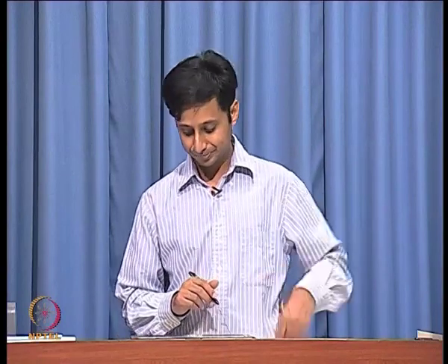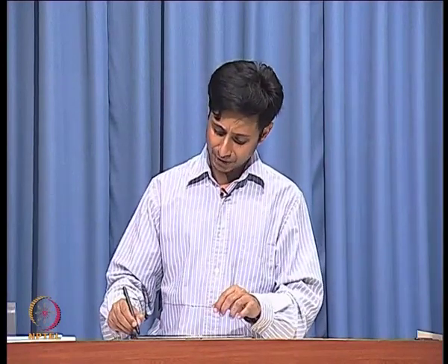So, what is your guess? How do you create a low impedance? If you look into the drain of a MOSFET, you see high impedance. If you look into the source of a MOSFET, you should see low impedance, right. So, you have to add a source follower over here. That is what is going to get you the low impedance that you want. All right. So, let us modify our design.